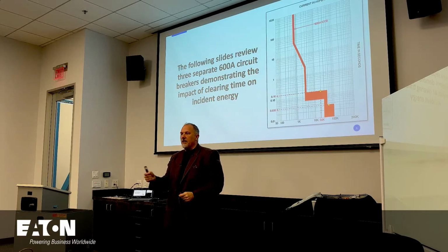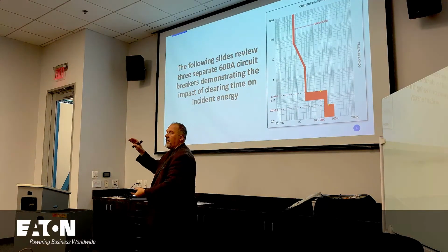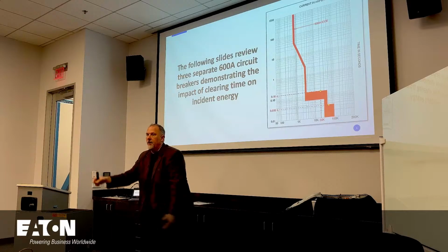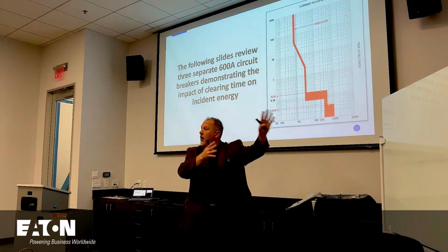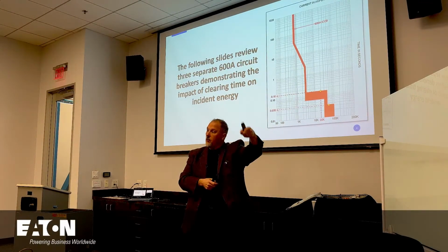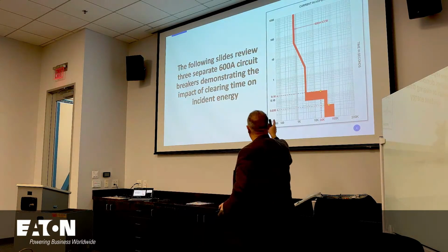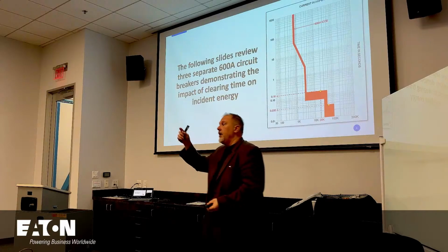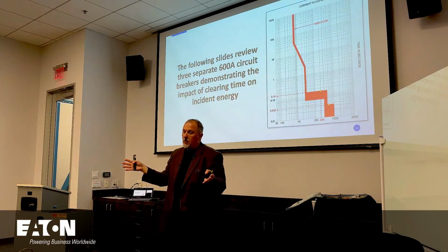So what I always tell apprentices, when you're in a power distribution system and you see little equipment, good. Big equipment, bad. Because the closer you are to the utility, the larger the equipment gets, for the most part. So, larger circuit breakers: I can buy a 600 amp breaker as a power breaker, 600 amp in the molded case, and everything in between.